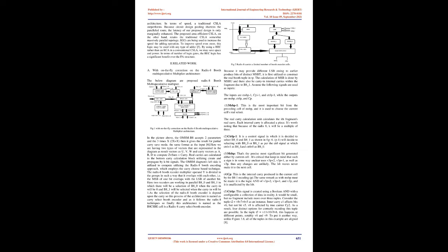The BEC logic has a strong benefit over the FA structure in terms of total quantity of logic gates. The primary aim of this proposed project is to examine the speed of addition while using n-bit BEC. This technique may also be employed to enhance the capacity of every adder further. In a traditional CSLA, we may save space and power by employing a BEC instead of RCA. The BEC logic structure has a significant advantage over the FA structure in proportion to the number of logic gates utilized. Proposed technique: the area power-saving CSLA circuit is altered by this notion.